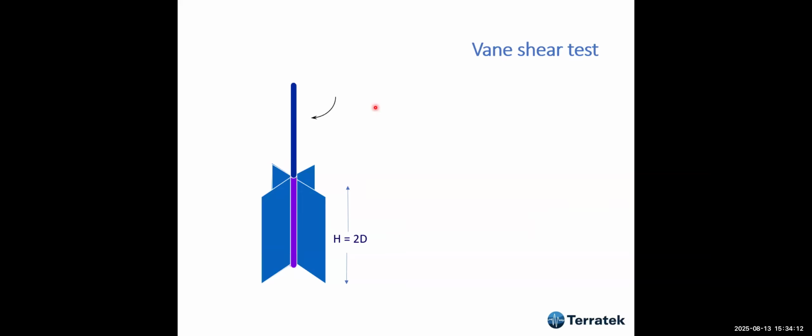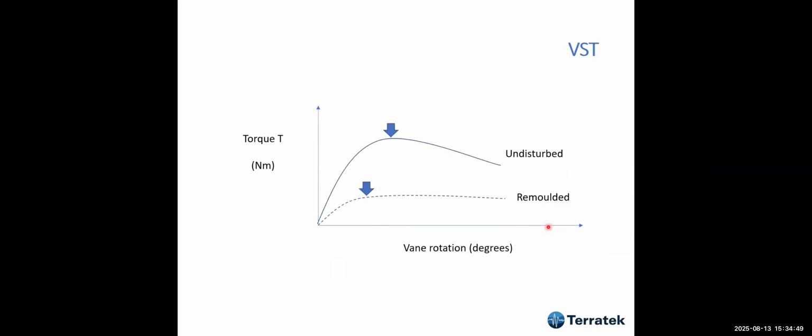This vane test was devised in 1919 by the Swedish, and in most cases, if you have the height of the vane equal to 2 times the diameter, you can calculate the undrained strength by this formula, in which T is the torque in kilonewton meters, and D is the diameter of the vane, and you do 2 tests.